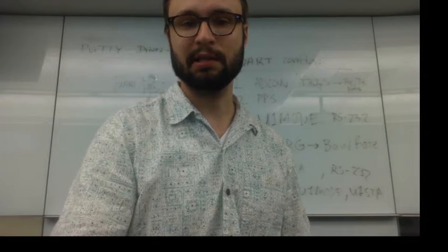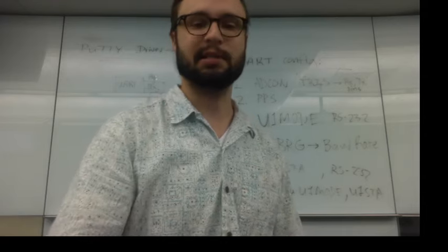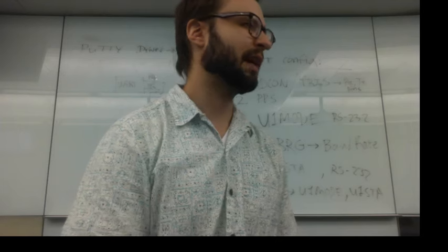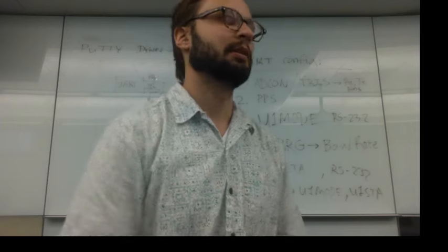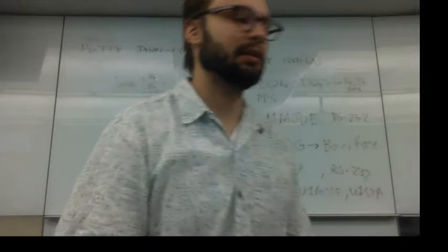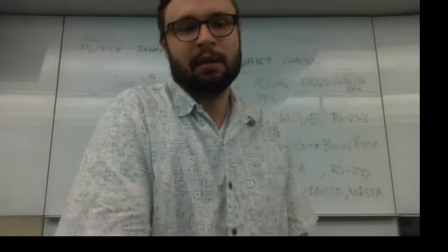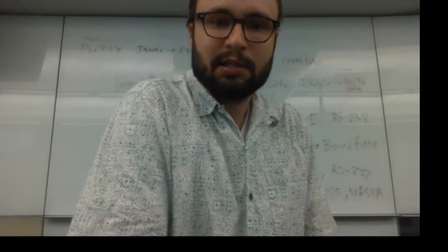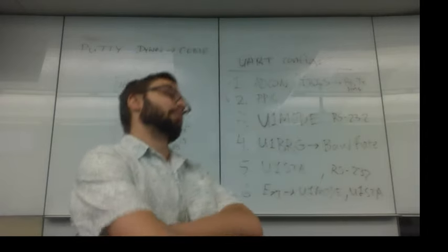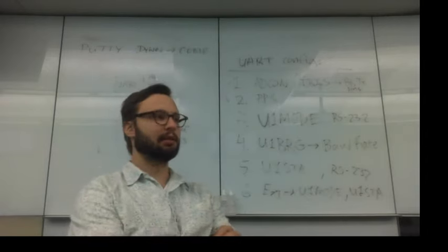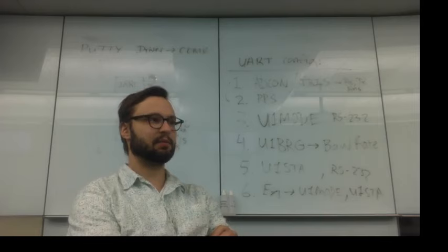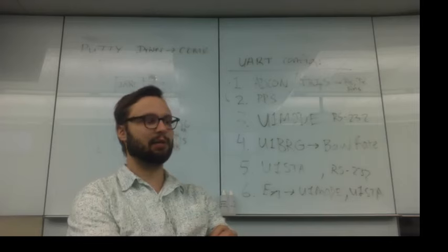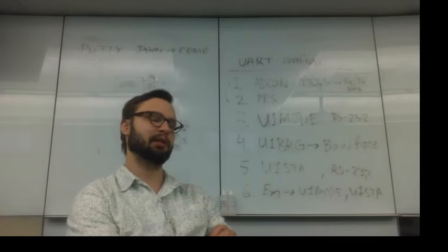But the thing is, it takes 2 instruction cycles. So it's no faster than doing a pop. I don't know why it does that. It is just 1 word of program memory, though, it says here. So with 1 word of program memory, you can do this. So it saves program memory. So I could see why the compiler would say, okay, we're going to do this. We're not going to do push and pop.